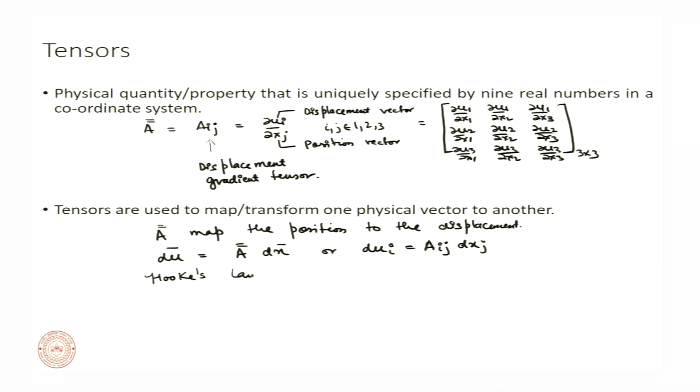The Hooke's law, the most common definition is sigma is equals to E epsilon. That is an approximation or a simplification to the first order. So it's a simplified definition. The actual Hooke's law is sigma is equals to C, that has 4 bars, into epsilon. In this case, sigma is a tensor, epsilon is a tensor, and C is called the stiffness tensor.